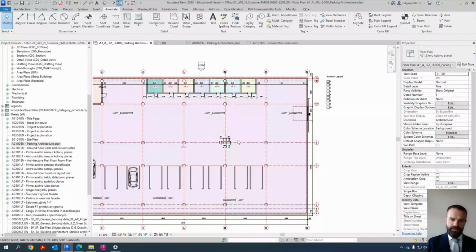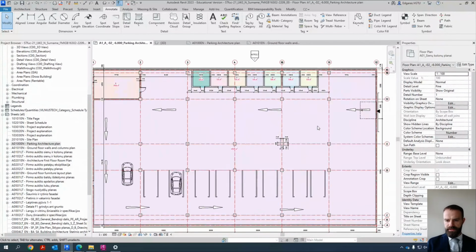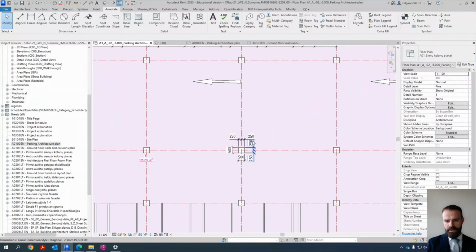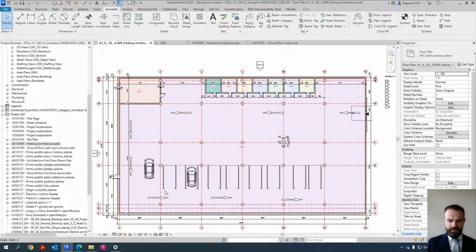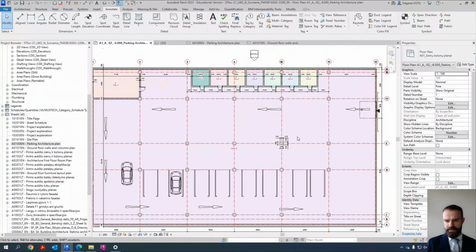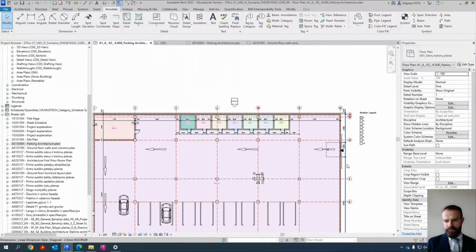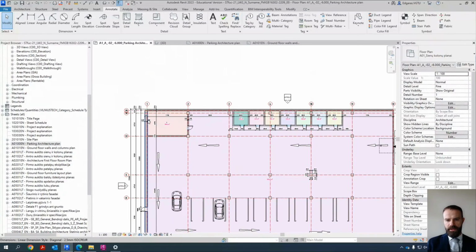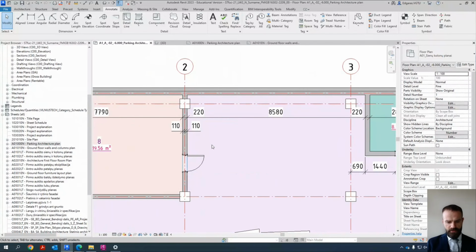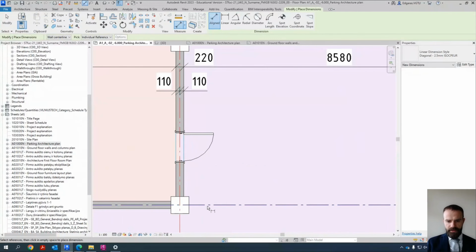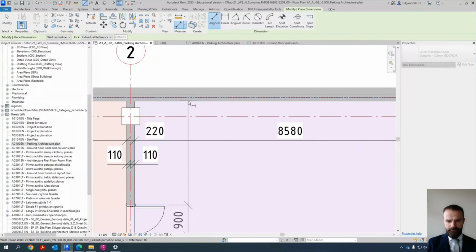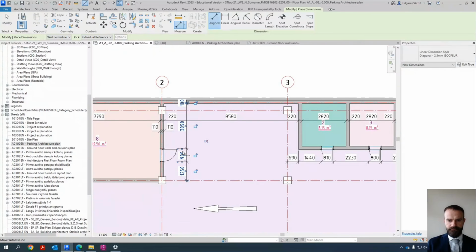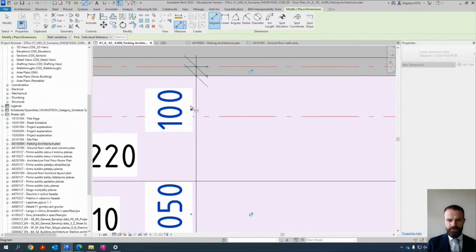If the columns are the same size in all the buildings, I can connect one column, which means other columns are represented with the same logic. If columns change or the position is different, I need to also show additional information. Now regarding these doors, also connect doors to the wall and the grid line and show dimension.